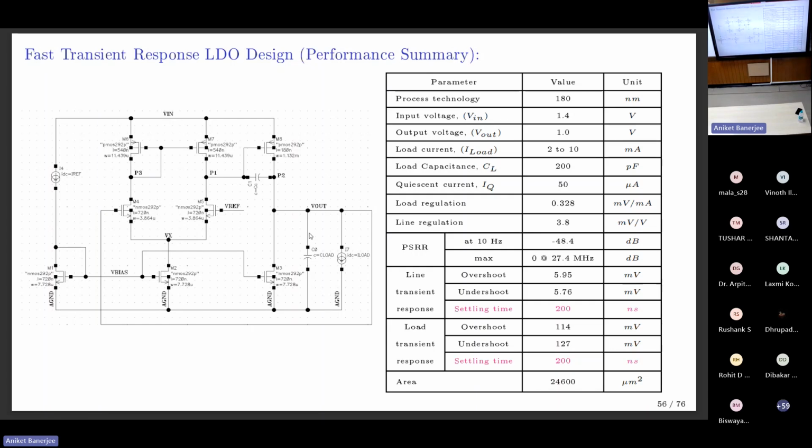So map transistor gm/ro, gm/ID, ID/W to this 50 dB and 200 nanosecond spec, like how it is shown. Arrive at all the W/L. In the first iteration, you meet the LDO performance, not just the DC operating point. LDO performance met.